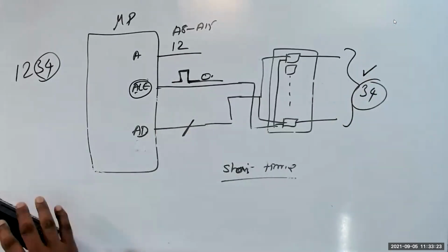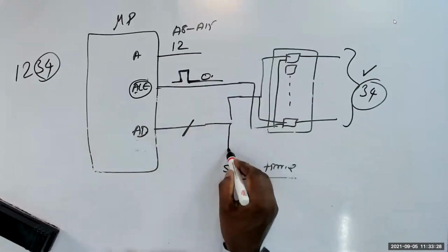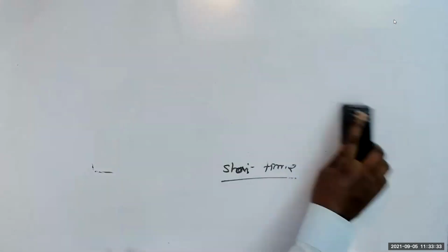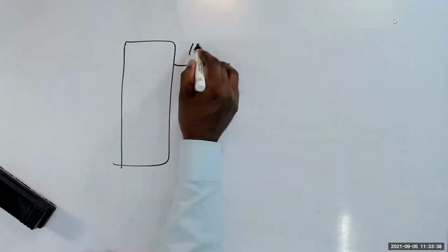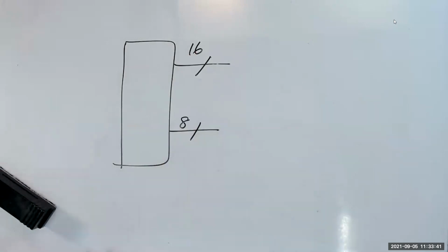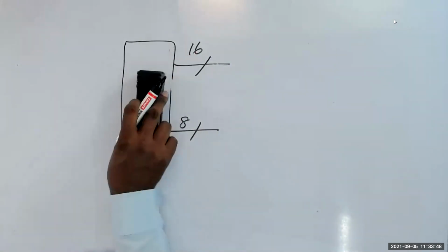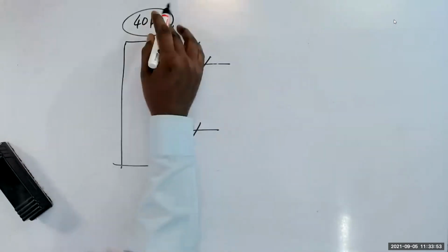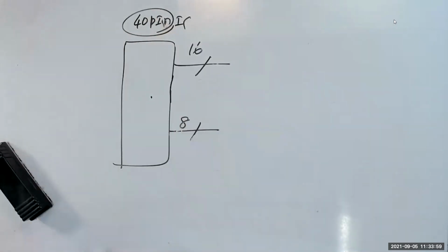So what we are trying to do is demux it. So afterwards, this becomes a data bus. So it's as we discussed all the time. This microprocessor has 16 address lines and 8 data lines. But please understand, instead of putting the mux here, they put it outside because they don't have space to make a 40 pin IC. They have to make a 40 pin IC. So they want to save the 8 pins. To save the 8 pins, they did it.